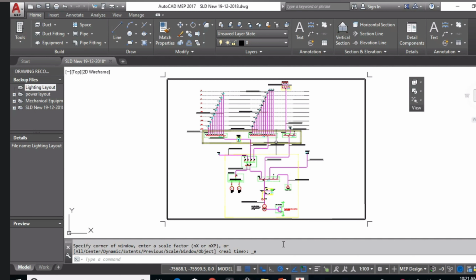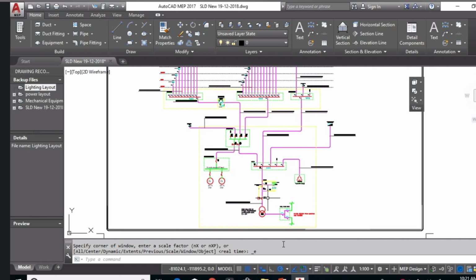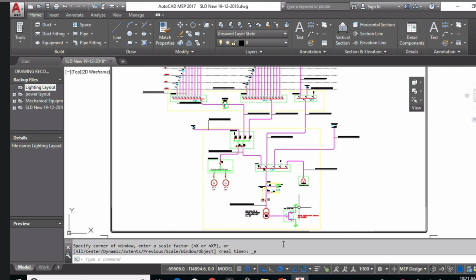And this is the single line diagram which I have designed specifically for the previous example. As you see here, I have a line coming from the medium volt side, and here I have a transformer, and here this is the MDBs, and here I have a set of backup generators, and here this is the ATS system, and all of these are sub main distribution panels, SMDB.